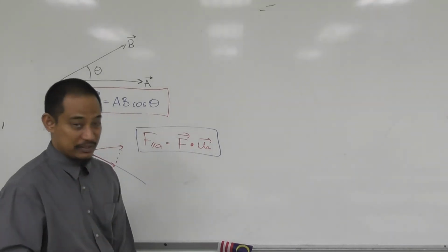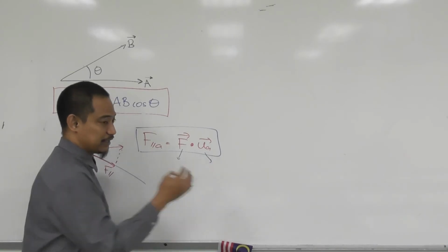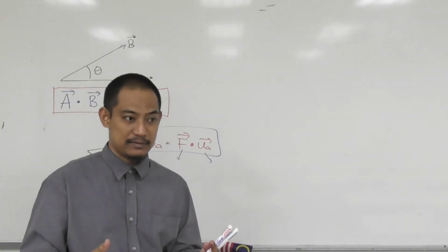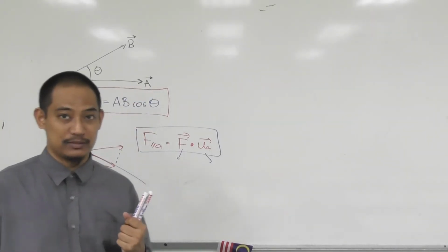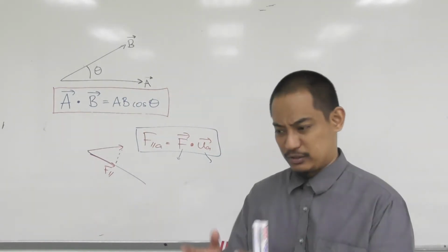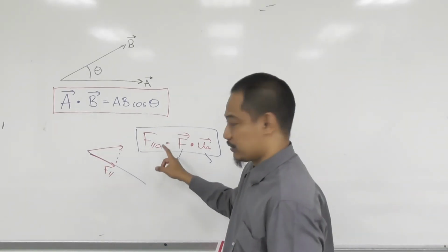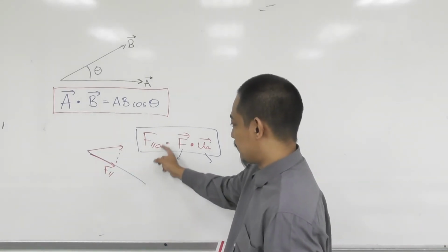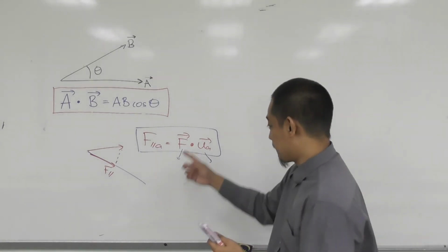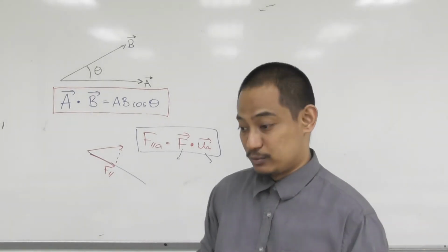Then what it means is, okay, I need the force in vector and I need the unit vector of the line, the blue line, right? So as long as I can get that, I can calculate using this equation, right? So that's the first thing that you should be able to tell. Before you calculate anything, what is this question? Oh, it's projection on a line. So I have this equation already in my mind. This magnitude is the original force in vector dot the unit vector of the line. So that's the only thing that you need to think about, right?